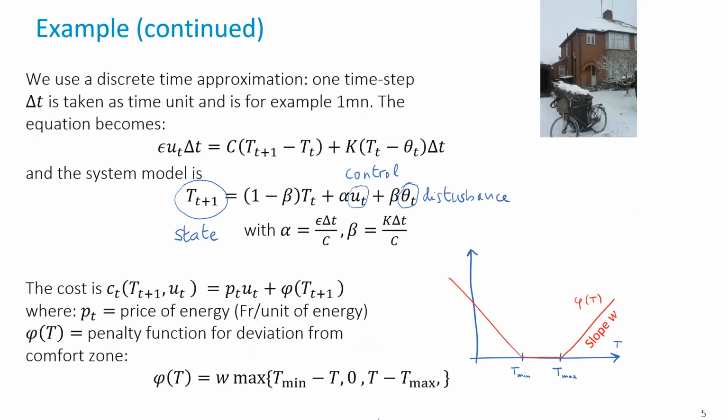That's the continuous time model. Now, because thermal systems vary very, very slowly, we don't really need partial differential equations. Simple discretization is enough. So if I replace dt by delta t, I go into discrete time. This is the thing I will have. The difference in temperature, that was dt before, becomes simply a discrete time derivative. So that's exactly the same formula that we had before. In this case, delta t is 1 minute, which for a heating system is probably already fairly fast.